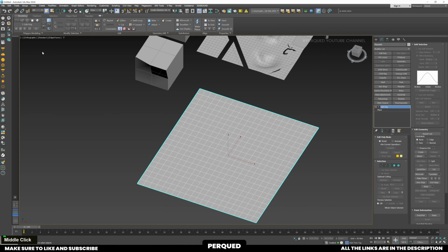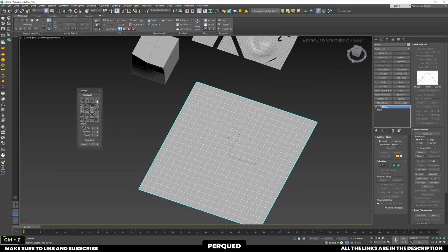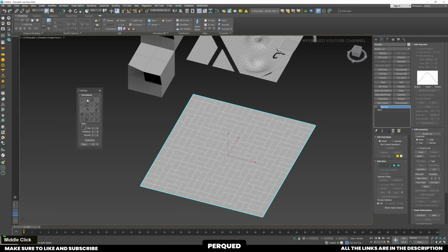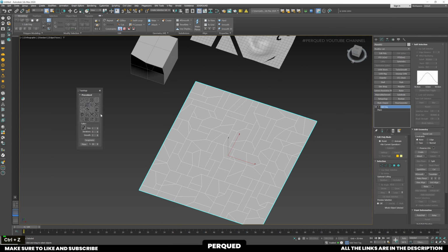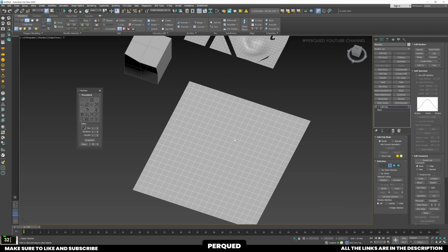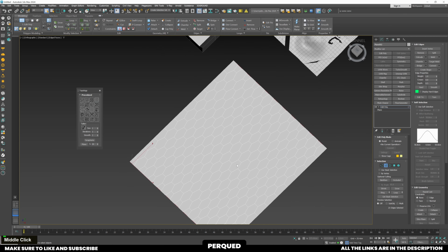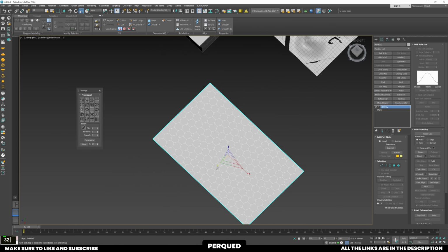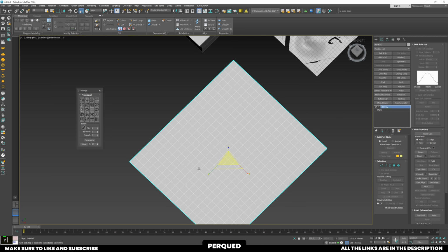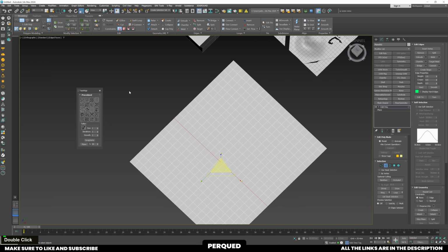poly tools. First, we have the Generate Topology tool. If you go to Polygon Modeling and click on Generate Topology, you find this. What this does is help you create some procedural shapes. Click on any of the shapes and you'll see it making a shape on the basis of how many segments you have in your object. Some patterns will not work unless you select an edge from editable poly. Just select an edge in editable poly if some pattern doesn't appear as you click on it. This is a very useful tool. Make sure to practice it.